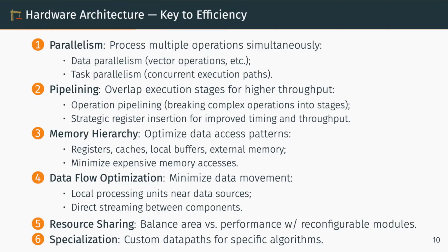Another thing is that even if some algorithm is proven to be efficient on the software side, on CPUs or GPUs, that is general purpose processors, it is not necessarily good for FPGAs, because of the inherent difference between general purpose processors and FPGA logic, since we have to design the hardware architecture here.